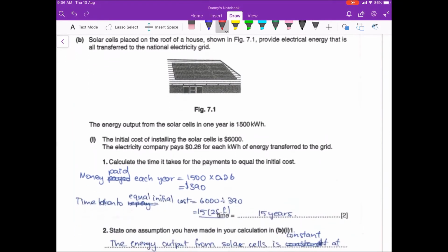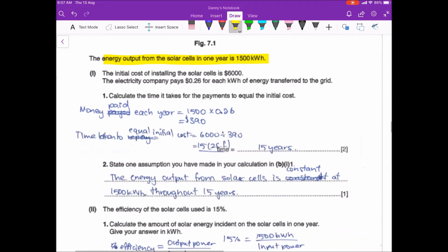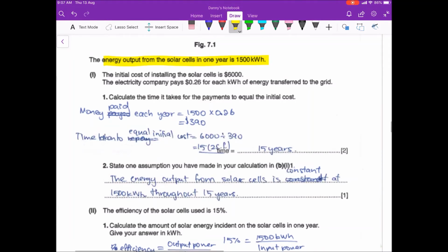So then B is about your solar panel. Usually solar panel is a heat transfer question, but this time around they turn it into a practical electricity question. You need to know how to calculate kWh and so on. Now pay attention, this energy output has already considered energy loss, things like that. So it is already averaged out. You are asked to calculate how much saving your solar panel can offer you, and when it will balance off the installation cost.